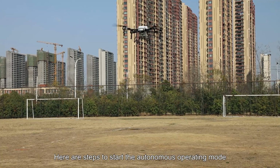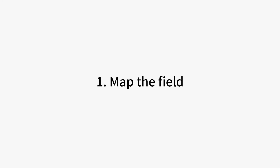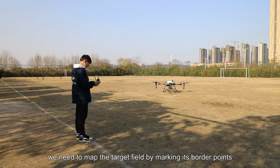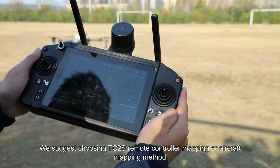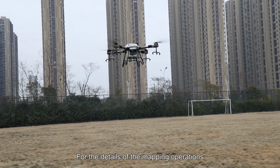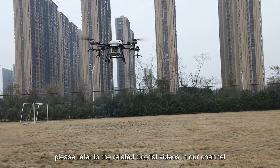Here are the steps to start the autonomous operating mode. 1. Map the field. Before starting the autonomous operating mode, we need to map the target field by marking its border points. We suggest choosing the TC2S remote controller mapping or aircraft mapping method. For the details of the mapping operations, please refer to the related tutorial videos in our channel.